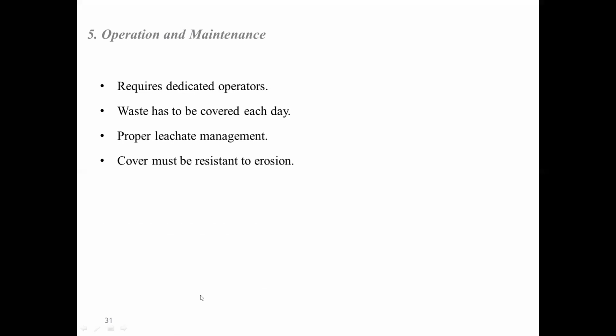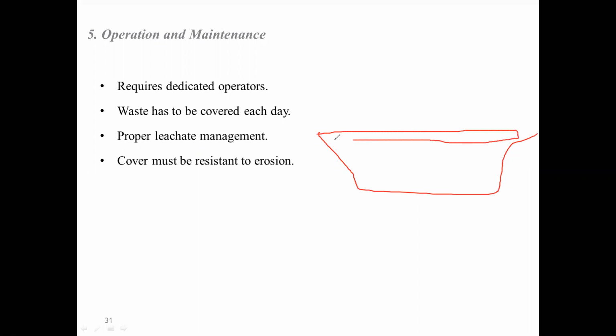Then the top portion is there. Those portions should properly be covered. The reason why we say this is resistance to erosion, because the cover must be so strong that it does not lead to any erosion. Because if you are not providing the covers properly, if let us say this is your landfill, engineered landfill or whatever you have, when it is covered, whatever topsoil you are putting should be restrained, or it should have a resistance against the erosion.